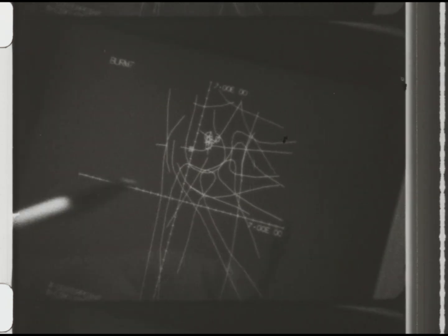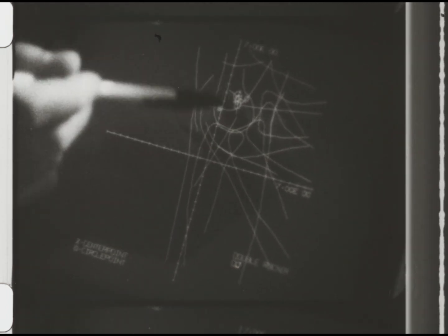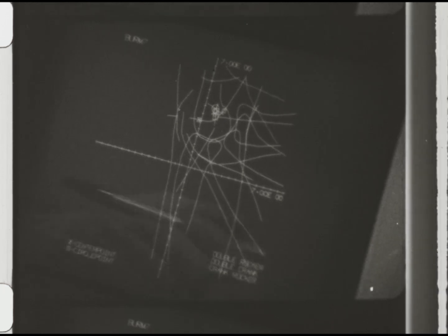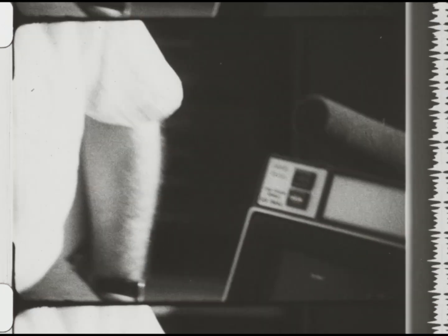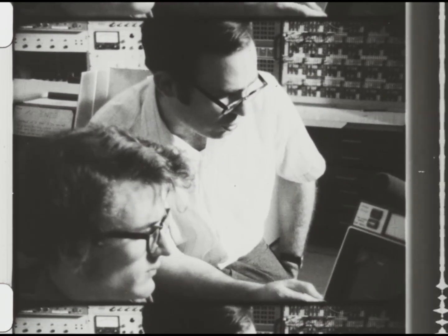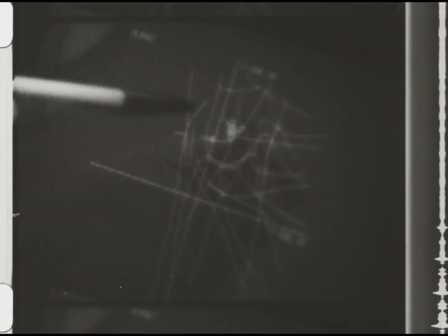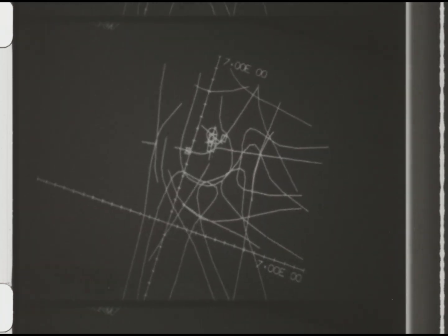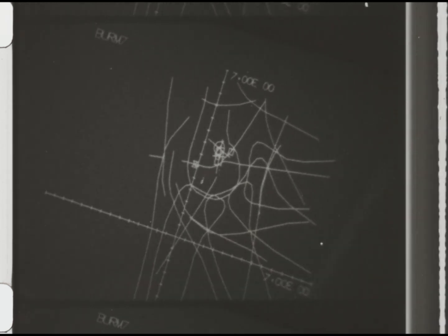For instance, we could select the slider point and one of these other circle points. A slider can be considered as a point which in each of the design positions moves on a straight line. In other words, it is actually a point whose center of curvature falls at infinity. And we have here 2 kinds of slider points. One we call a concurrency point, the other a slider point. And these can be used for designing slider crank mechanisms of the different inversions, either turning block mechanisms, tumbling block mechanisms, or slider crank mechanisms.